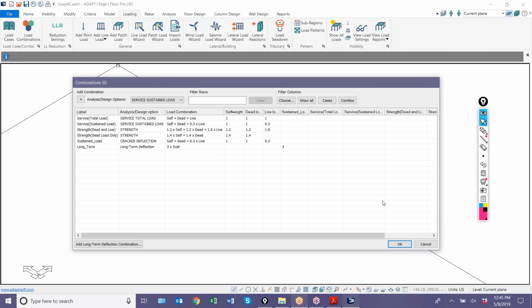If it's a post-tension slab, then the minimum rebar for positive bending regions is impacted by the stress level. So in your case, you would have to run the model with only gravity level combinations, for example, determine the amount of rebar, and then without gravity and with lateral and determine the rebar. It would have to be run twice.